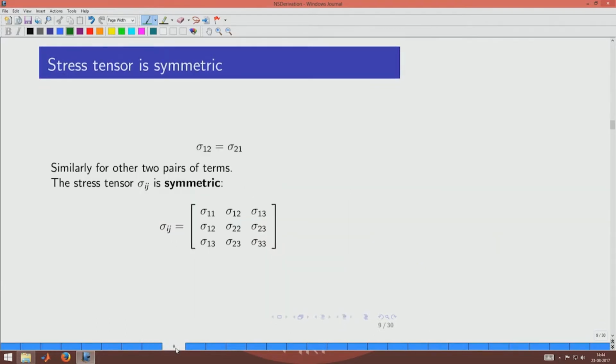So, we say that if sigma is a symmetric tensor, we now have written here sigma 1 2, sigma 1 3 both ways and sigma 2 3 both ways, which means that we now have 6 components that are to be determined. Okay. So, from 9 we have got 6. So, there is some progress. Okay. Now, let us go further and see what can we do about this.